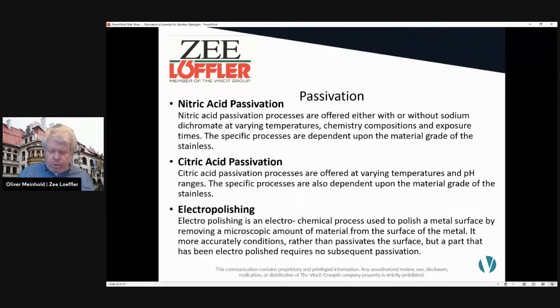But like I said, you use it in a much lower concentration, you more clean it, and then you basically rely on the oxygen. I was talking a while ago to the German Federal Material Research Center, and an 800 to 1,000 barrel tank needs, after citric acid passivation, about 2 weeks to get fully passivated. You have to ensure that the air is always saturated with about 21% oxygen. So you have to attach a blower to the tank and make sure there's always fresh air going in, because the oxygen will decline as it reacts with the chromium, and you have to make sure it comes back in a proper concentration. But like I said, it's a very long-lasting and sometimes not really well-defined formation of the layer.